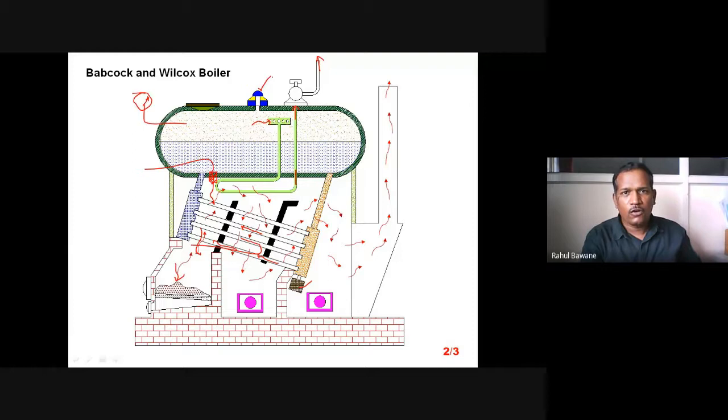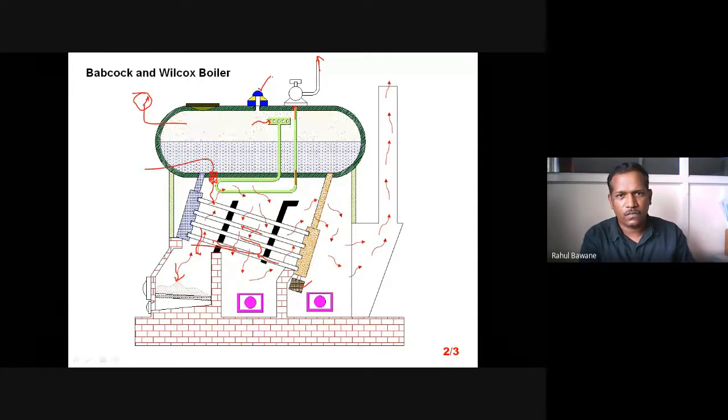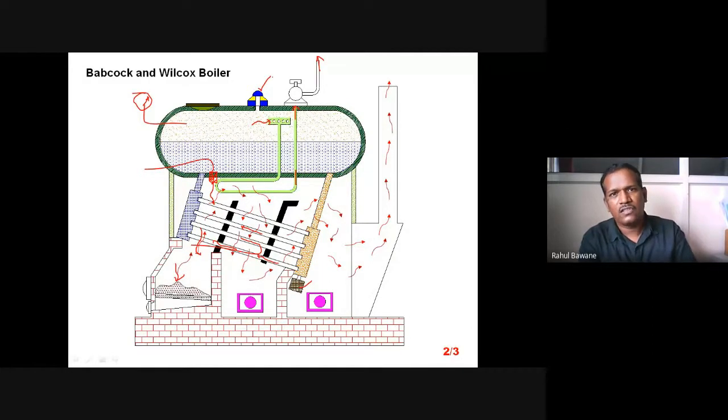That means however much weight that vessel has, that much pressure will build in your pressure cooker, and that weight is dead weight because it is not going to change. So that kind of safety valve is known as a dead weight safety valve. We will check out how these valves and all these accessories work in detail in the next session.